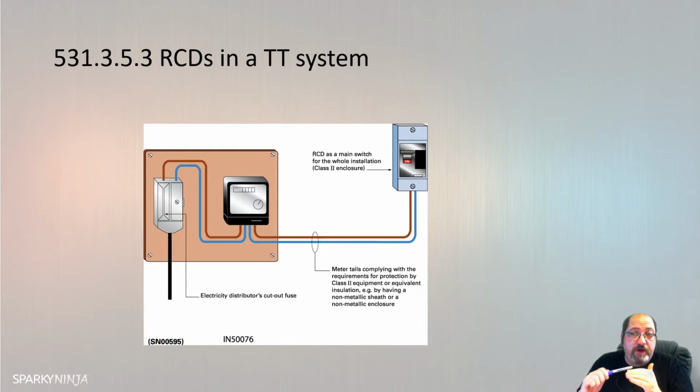So that's 50 volts. So when you're looking at a table and you're thinking, how does this add up? What you've got to say to yourself is, right, 50 volts is the maximum. So if I say, right, I have 50 volts, and they've made an RCD at 20 amp on the shelf. Well, 50 volts, Ohm's law, over a current of 20 amp, what is the value of resistance that would be needed?